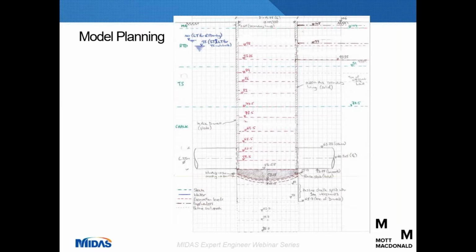So remember, a model is an approximation of reality. So for example, this is a sketch that is more detailed on the actual section through the shaft itself. And you can see that there's a transition in ground stratigraphy, the green lines, at 77.5 meters between the Thanet sand and the chalk. So therefore, it was decided to simplify the model to put an excavation dig stage there as well, so that those are coincident lines. And you'll see there's various points in the model where the geometry has been rationalized to simplify down the mesh.